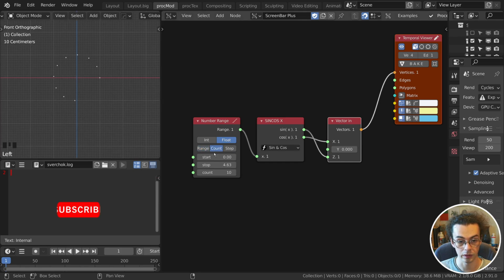If I change my number range to count, then we have a certain number of nodes, and we can now set the start and stop points. I'm going to just set mine slightly below the center, more or less horizontal. This doesn't matter too much. It's just basically to give me most of a circle and then a flat section.